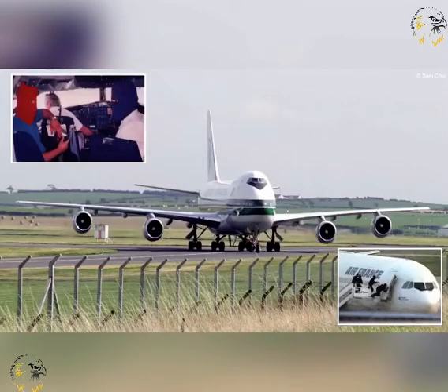All commercial aerodromes must have a designated, isolated aircraft parking position that can be used to park an aircraft that is known or believed to have been subject to unlawful interference, or which for any other reason needs to be isolated from the normal day-to-day aerodrome traffic. This area must be at least 100 metres from any other parking area, building and public area, or over or underground utility service.